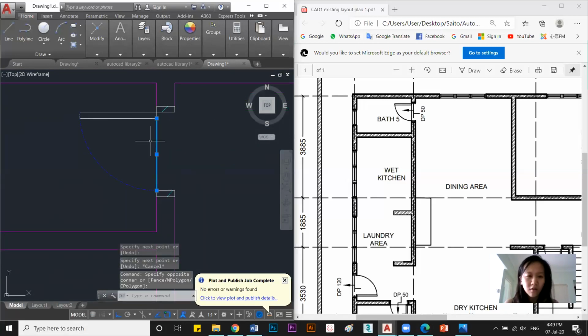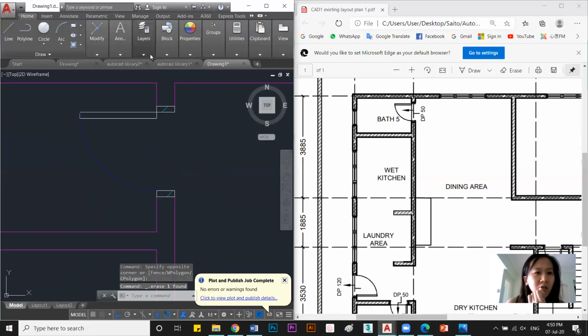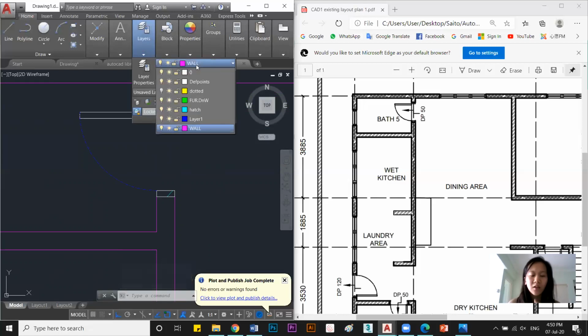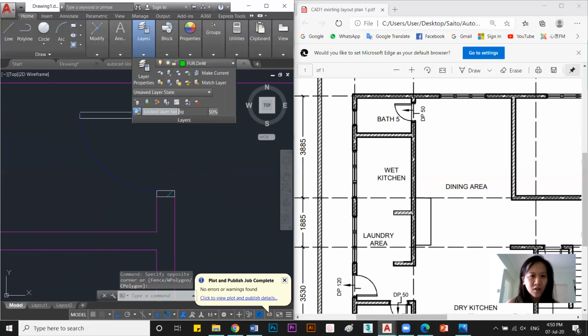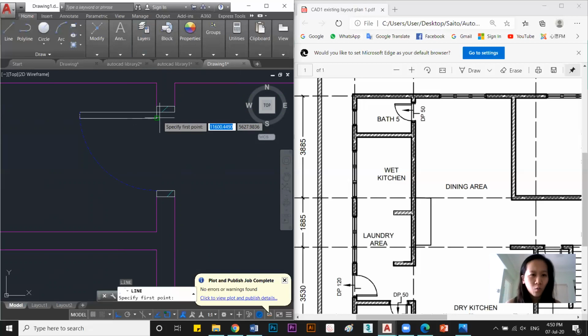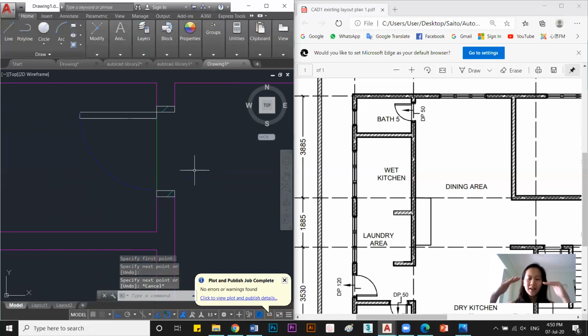Use the wall to draw it back. Not wall. After the door opens, there is no more wall, right? So you just use the furniture. It's actually the floor line, because it's a bathroom, so it's one step down. If you don't have the line here, that means it is flat and the water will come out. So you need to draw one line here so that it is a step down.